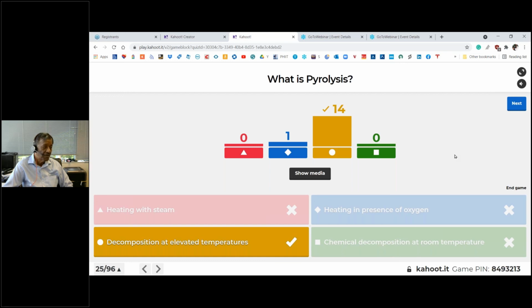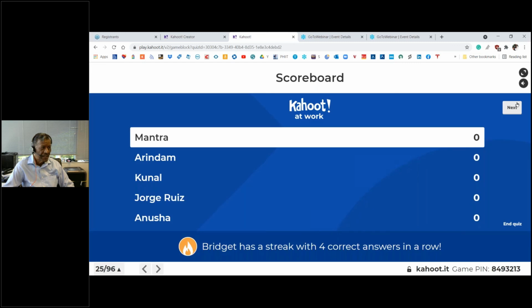Dilution steam, although it does not take any part in the chemical reaction, does help in improving the yield of ethylene by reducing partial pressure, as well as in coking. So that is the basic pyrolysis, what is taking place inside the radiant coils where the reaction is taking place.